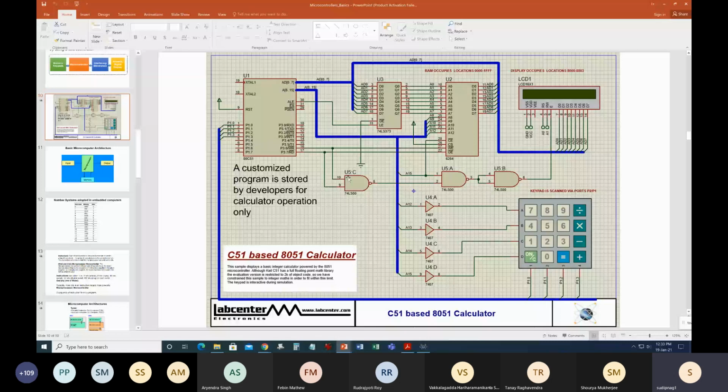Now look at some similarities with what we just discussed. The 8051, port 0 and port 2 are basically over here, and they are connected. So whatever number of address lines you need, you just take out those many lines and ignore A13, A14, and A15 over here. This is the address latch enable that was used.